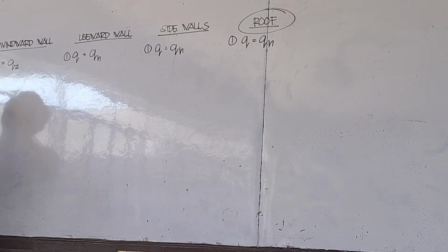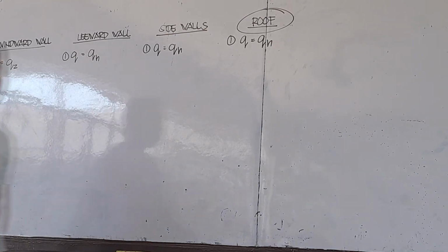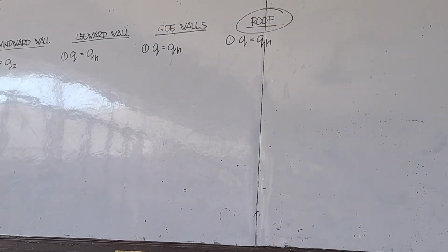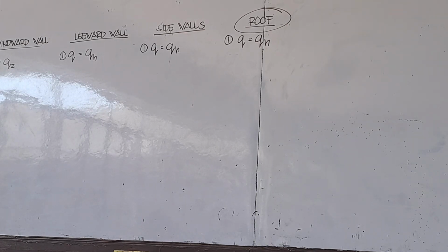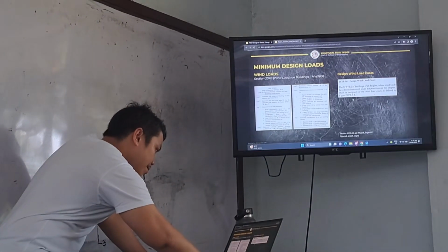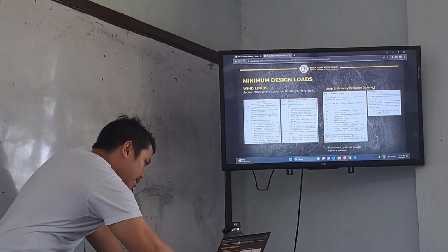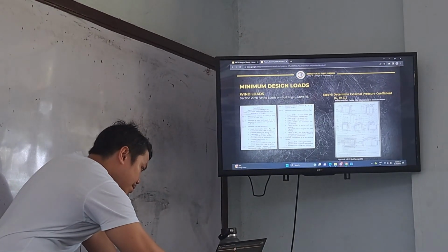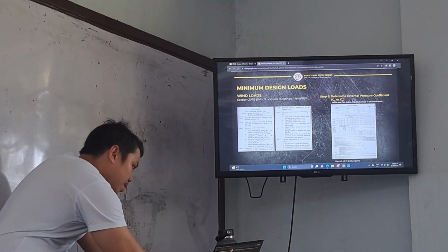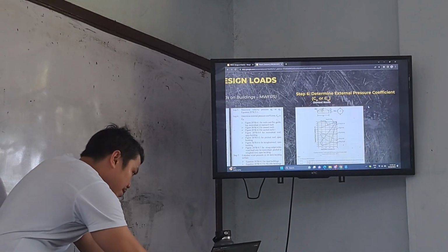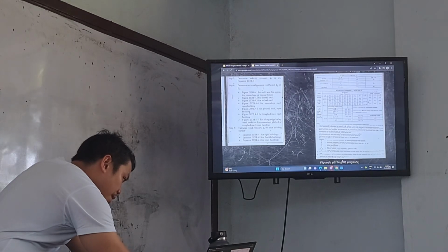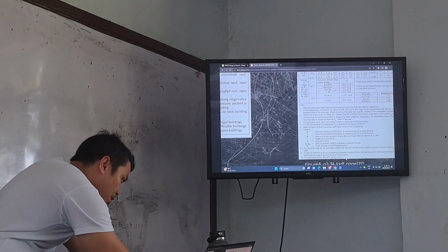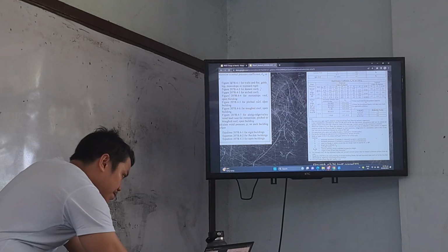Second, our Cp for the windward wall. You can find it in the NSCP, in the figures on page 2-74.